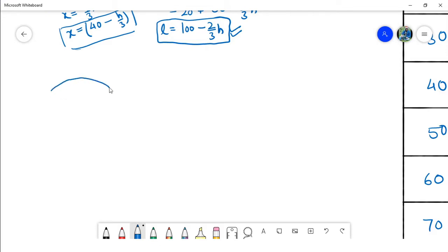Since we are required to calculate the constant radius arch dam, we are also required to determine the radius. In order to determine the radius, let us say this is the arch, and this is the external radius. Say this is the center. Based on this, this is 2 theta, and 2 theta in this case is 150 degree. This is the external radius RE, and this is the internal radius RI.